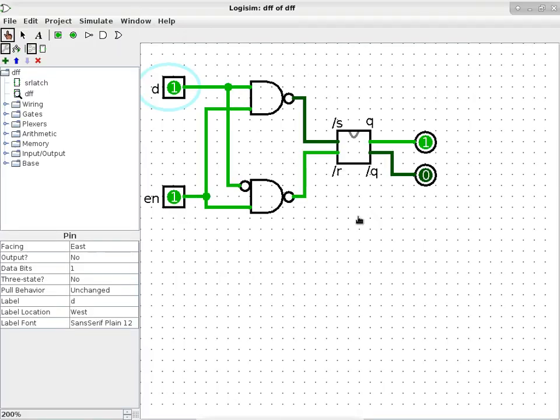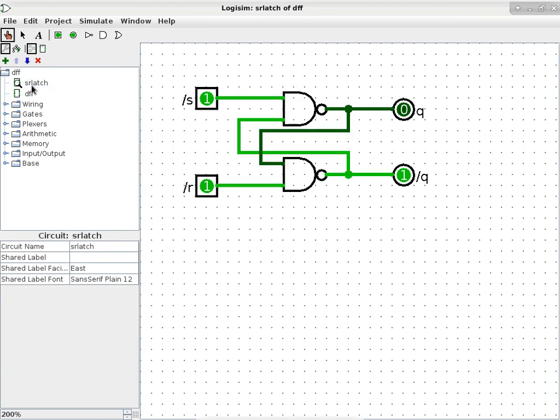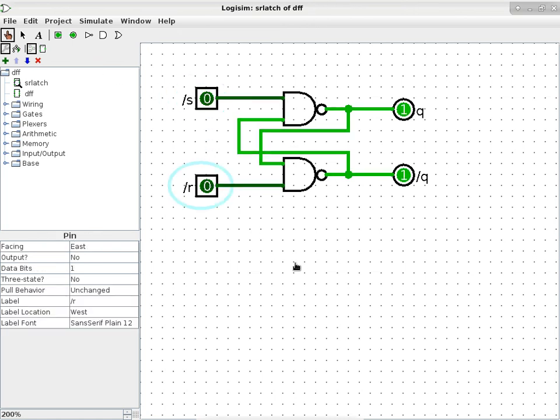In fact, we can benefit a little bit from the other class, so we'll take a look at the SR latch first. This is called the SR latch. And what do you notice about this circuit that is kind of different from all of the other circuits that we have talked about in this class? And that includes the 3x3 carry look ahead mechanism and whatnot. Yep. The output of each gate is an input to the other gate, so it's reliant on each. Yep. On each gate. Yep.